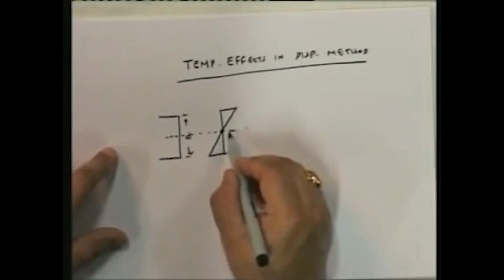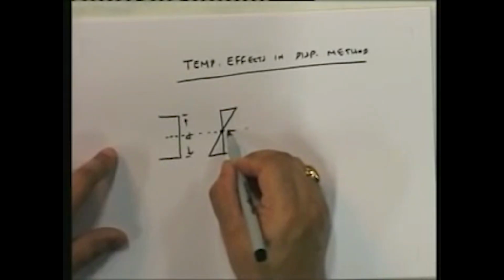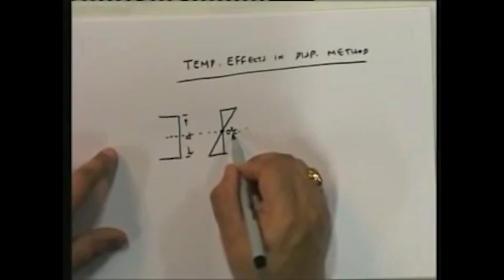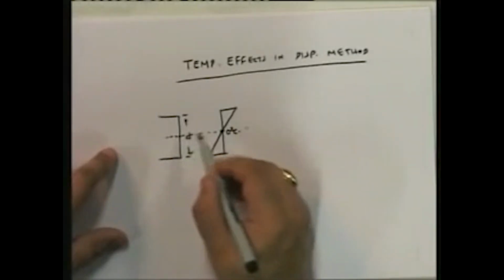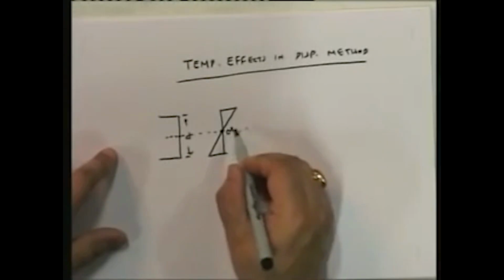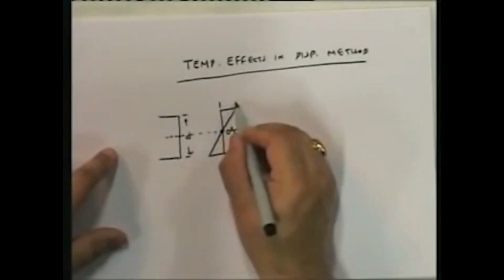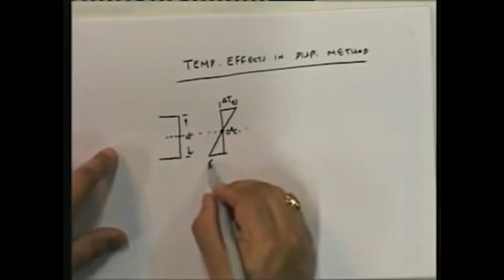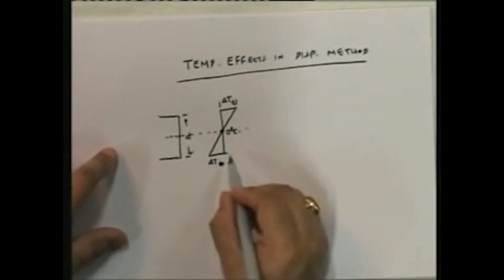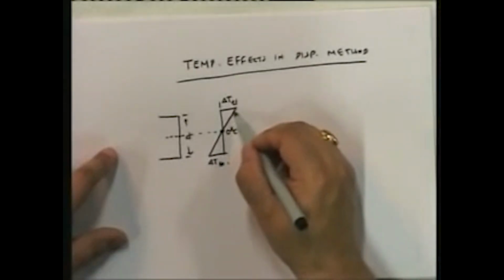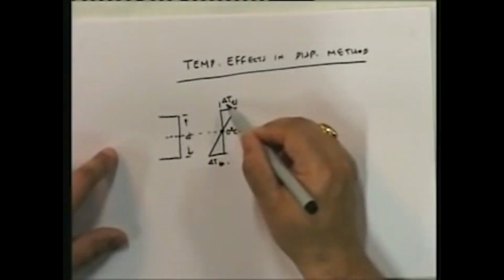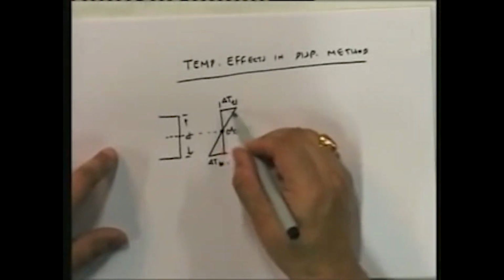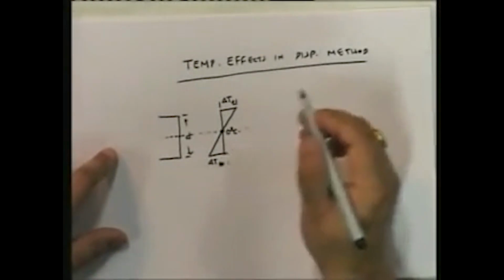At the neutral axis, temperature is 0, the temperature difference. This is delta T, by the way, so it's not as if at the center you have freezing. It's just that there is no rise of temperature at the neutral axis. Here you have delta T at the top, you have delta T at the bottom. This is only the differential part. In reality, you might have two parts to it. I am only looking at the differential part because that's the one that causes flexure.